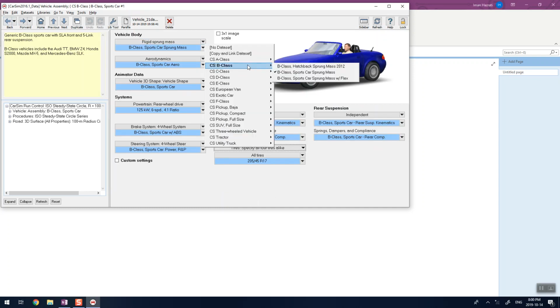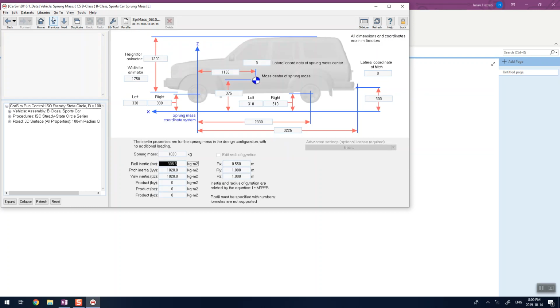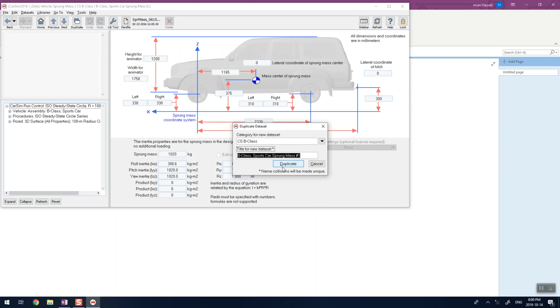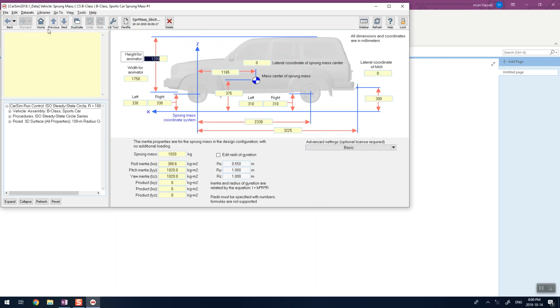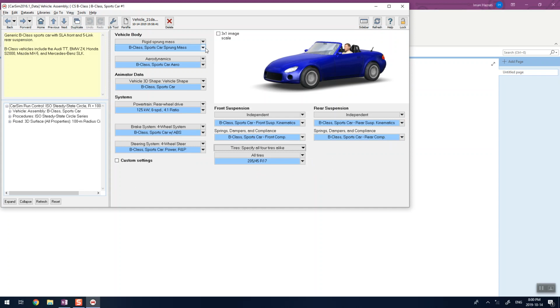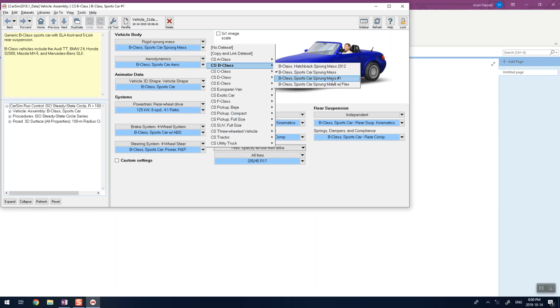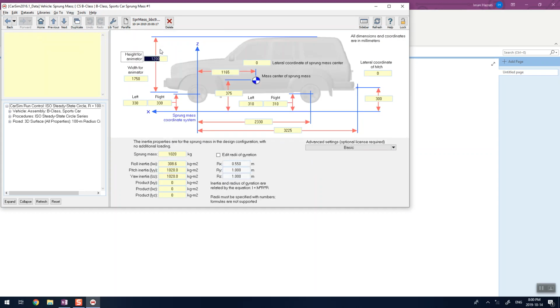You see that you can define any other software since we want to have a space model. Let's go for this B class model, duplicate it, give it a number 1 here, going two times back, reaching here and selecting the one I want. So this is unlocked. If I change it, it will be changed under the unsprung mass properties of the B class car dash number 1.